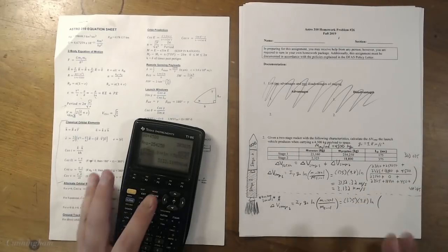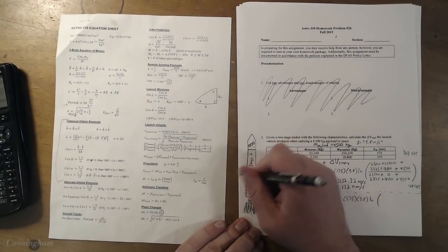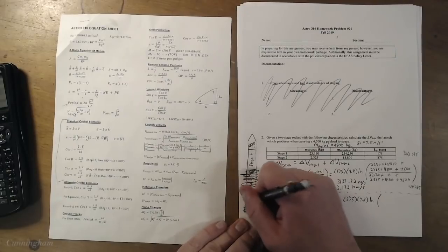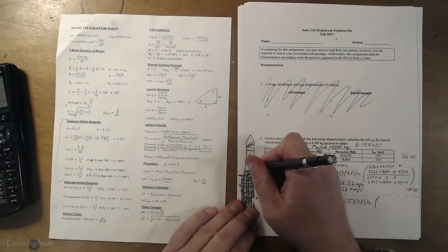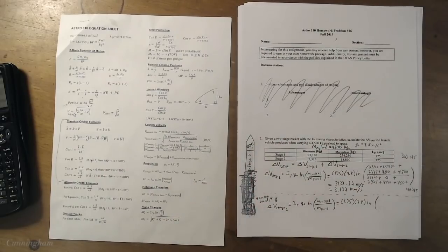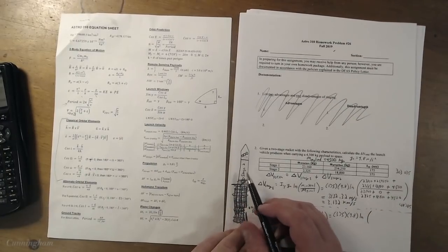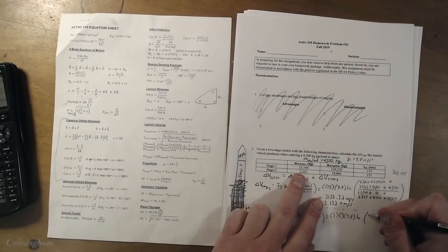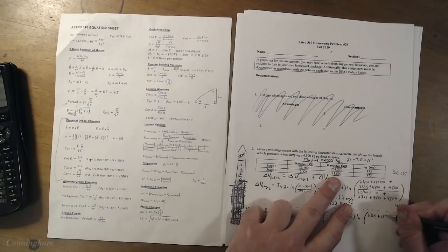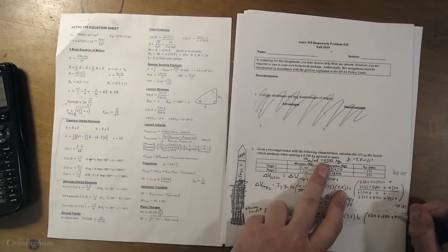By the time we've gotten to stage 2, stage 1 has not only burned up all its fuel, but it has fallen away. That's sort of the point of staging. You let go of all the mass, right, from stage 1. So really, M initial for stage 2 is just the mass of stage 2 and the propellant of stage 2 plus the satellite. So here we go, structure of stage 2, propellant of stage 2, and of course the satellite, we hope, is still attached.